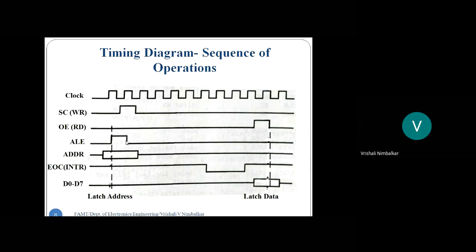So after deactivating ALE, deactivate SOC. It means the conversion has started. Okay, and now wait for the time and keep on checking end of conversion, EOC.